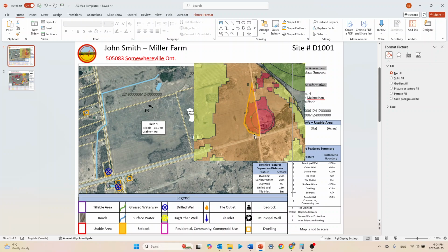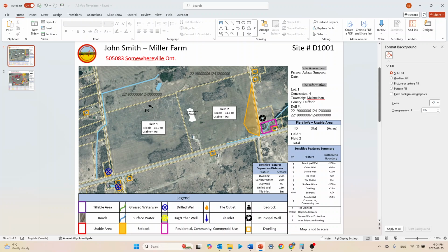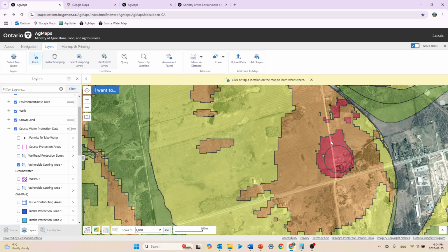Alright, so I can see that area covers up the appropriate setback. Now the trick is going to be, this is more of a complex one, that you're going to have to figure out a way to properly mark this so that whenever you're in the field and need to set this back, you can properly identify where these lines go. One way of doing that would be to go to your map and use things that don't change and include measurements on your map. So for example, the edge of the road to the tip of my setback is going to be 480 meters.